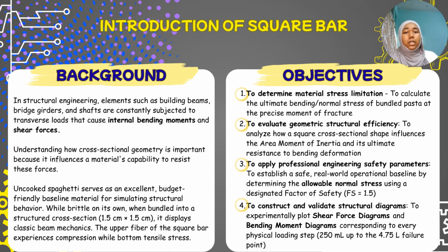Our third objective is to apply professional engineering safety parameters to establish a safe real-world operation baseline by determining the allowable normal stress using a designated factor of safety, which is 1.5. Our last objective is to construct and validate structural diagrams, which is to experimentally plot the shear force diagram and bending moment diagram corresponding to every physical loading step in our experiment, from 250 ml up to 4.75 L, which is our failure point.